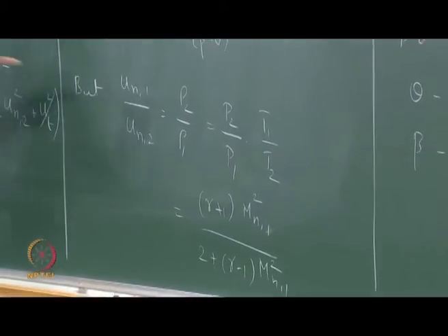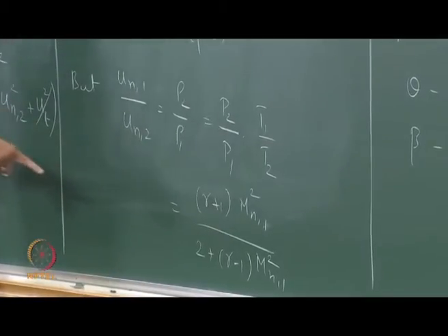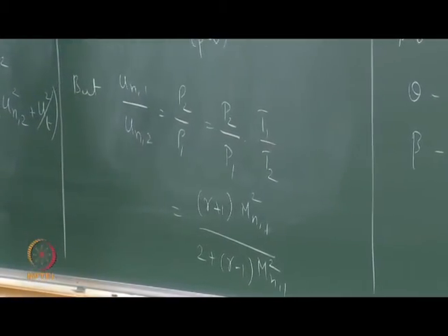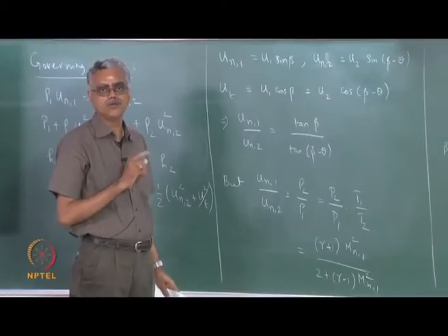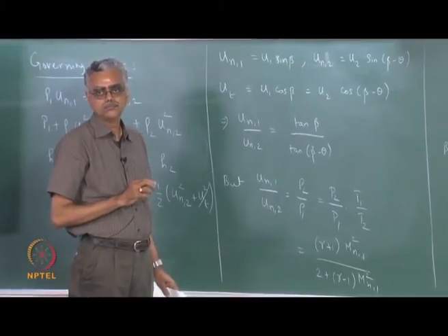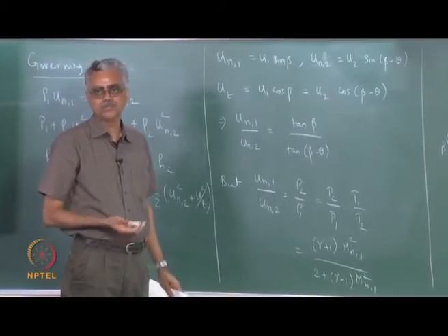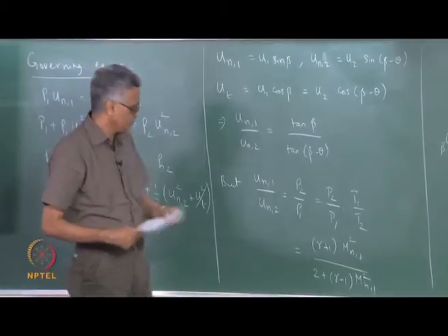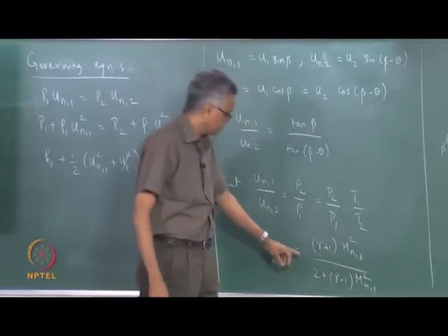So, the right hand side we have obtained from normal shock relations after replacing the M1 and M2 there with Mn1 and Mn2. Remember, we knew Mn2 also; we had eventually solved the equation. So, we know Mn2, and I have written everything in terms of Mn1.